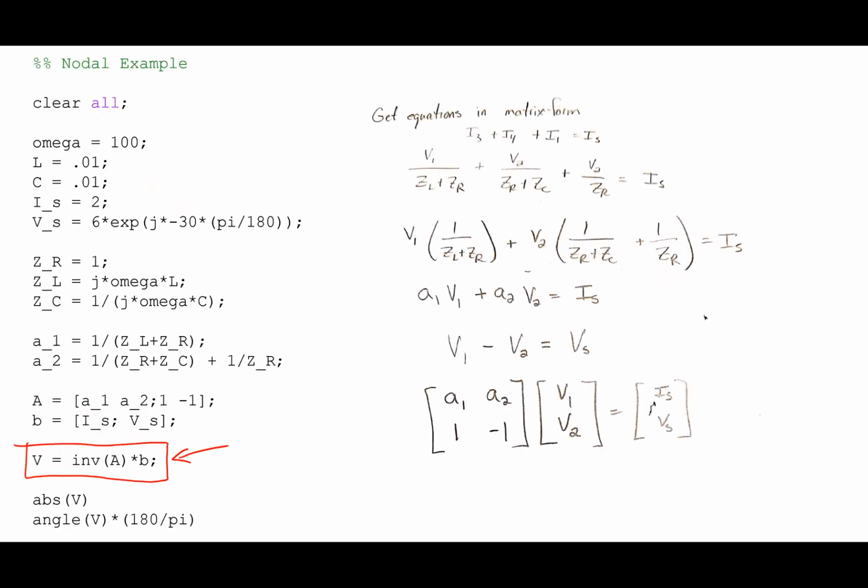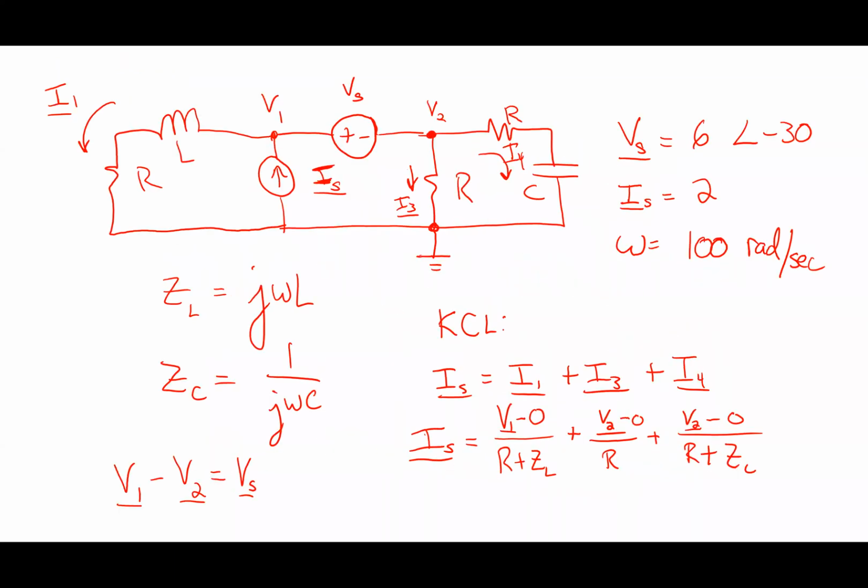We did a lot there pretty quickly, but the important takeaway is that nothing is wrong with everything I've done before. I can get all the matrices and so on, it's just all complex now. That's the only real difference in this case. One thing that'll confuse you is that the capacitor impedance will often be shown as negative. I say 1 over j omega C, but remember, that's the same as negative j over omega C. That will screw up your equations a lot, so be wary of that.